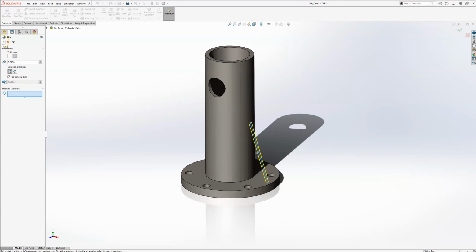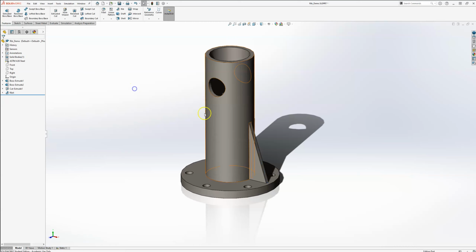Now notice when I accept this feature, SolidWorks is going to pull that line again down toward the other part geometry and create the rib feature itself there. So notice how quick that was to actually create that rib geometry. I didn't even have to have a sketch that had a closed profile there. It was just a single line there describing this outer geometry of the rib.